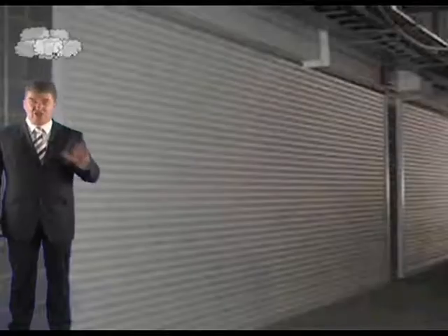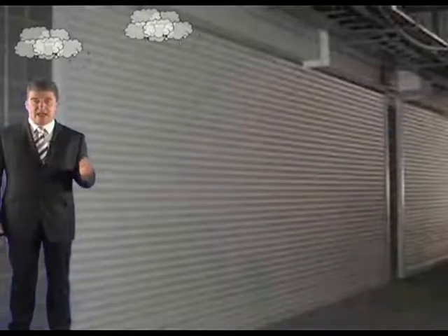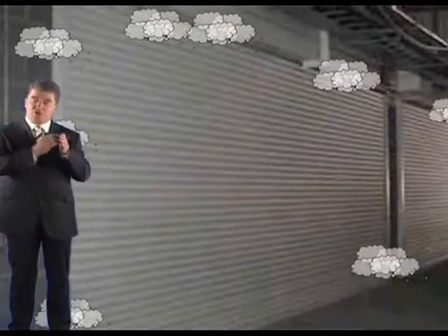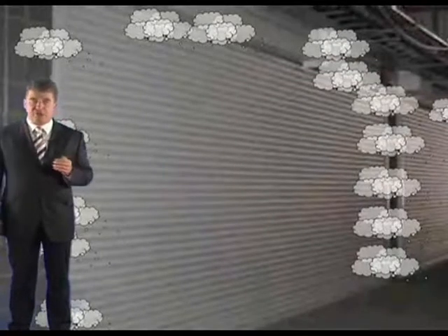Passive compartmentation such as doors, shutters, walls and floors can all provide some protection against smoke penetration. The extent to which smoke leaks through these barriers depends on the size and the shape of the leakage paths and the pressure differentials across them. In a larger fire, it will create a greater pressure, so it's more likely going to leak more than in a smaller fire, which has a lower pressure differential.